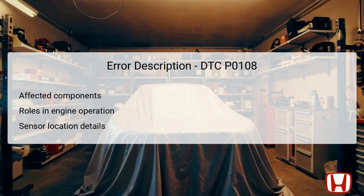operability. The components affected by the DTC P0108 primarily include the Manifold Absolute Pressure MAP sensor and the Powertrain Control Module, PCM. The MAP sensor is responsible for sensing manifold pressure and converting this mechanical measurement into an electrical signal. This signal is essential to calculate engine load, affecting fuel injection and ignition timing for performance. The PCM utilizes this information to manage engine functions effectively.